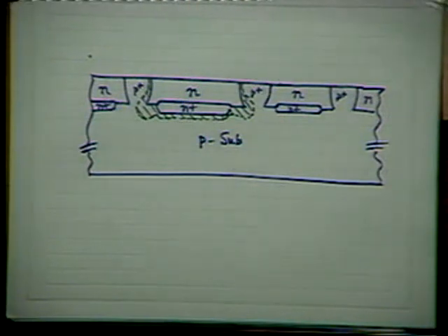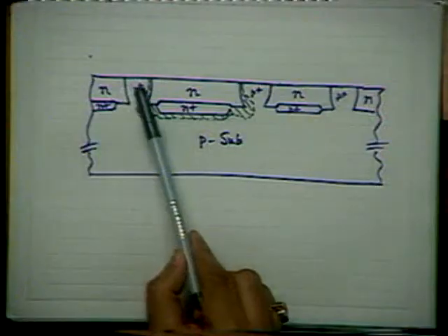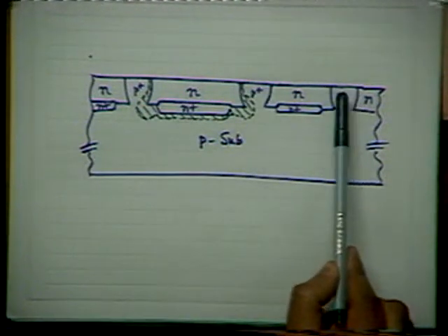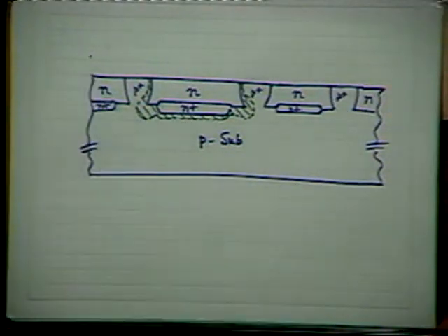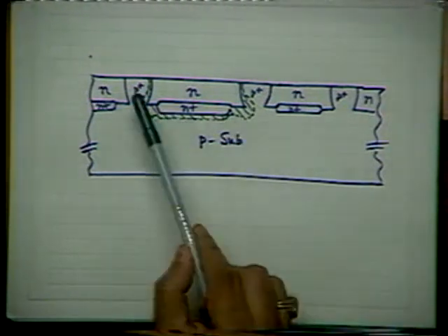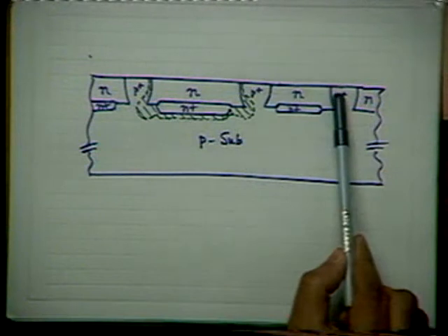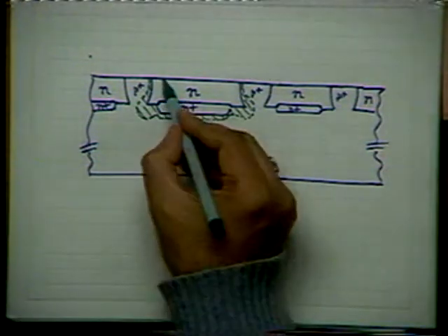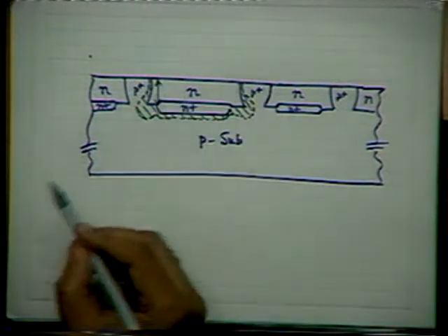So can I do something now to improve upon it? What people do is as follows. They cover it by an oxide first, and they do some, I will not go into the details of technology in this course because it will be unnecessarily taking time. By a very special technique, they first remove from this region about 50% of silicon, etch off. By using a photolithographic technique, they etch off from the P plus regions about 50% of silicon. By 50% I mean 50% of the epi layer. So up to this it is removed.